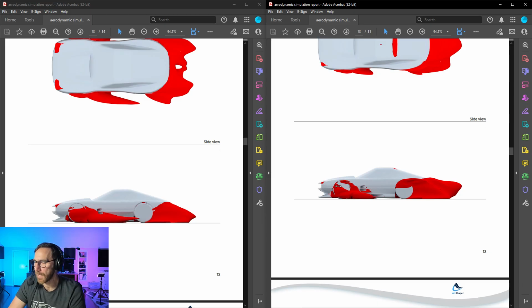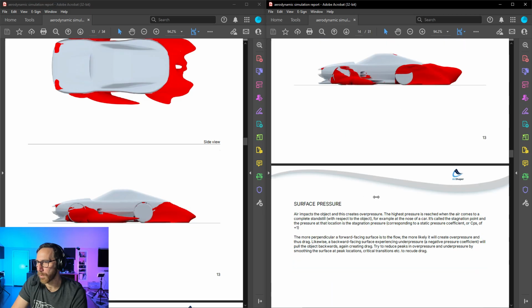As we look here, essentially it seems like the air handling to try to disrupt this is working. There is some brake ducting happening behind the wheel, not really going to do much for us because the wheel is just a cylinder right now. There's no way for the air to pass out of there. But these ducts, which are bringing fresh air from the front and trying to break this away from the car, seem to be working. This one right here could come further forward on that rocker area, but having it snake around the wheel well causes it to be at a funky angle. So in order to get it pointing backwards and not out sideways, it really needs to be in the middle of the car where it is.